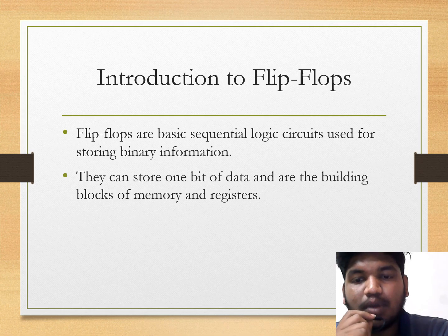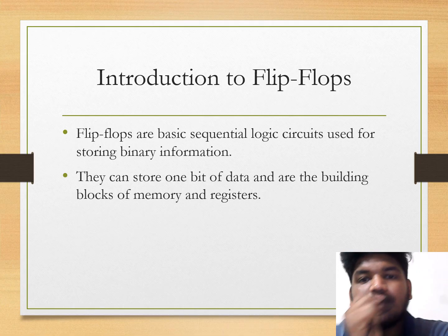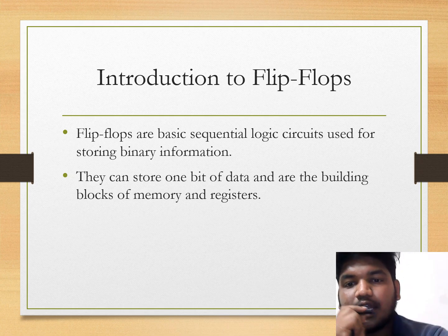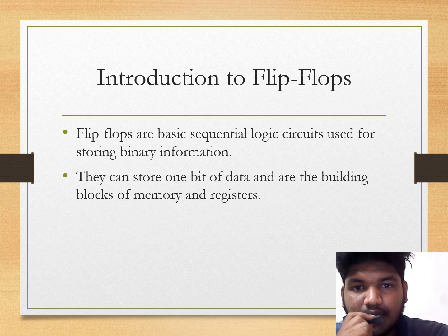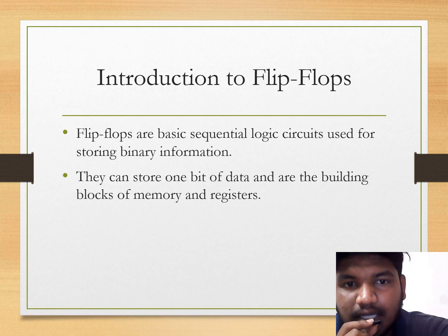Flip-flops are not combinational circuits. It is a sequential circuit, and it is used to store binary, and it can store one bit of data, and they are the building blocks of memory and registers. For flip-flops we will have a clock, two inputs and two outputs, that are present state and next state. Then we have many types of flip-flops, which we will see in the next slide. And this is the introduction of flip-flops.